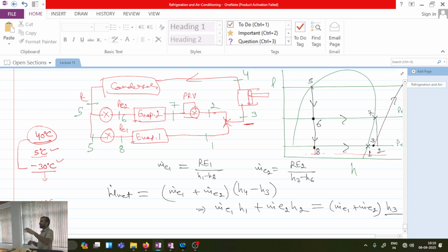As long as we keep on decreasing the pressure of the lower evaporator, what will happen? If I just do the expansion from the same state, then the throttling loss will keep on increasing. At the entry of the lowest temperature evaporator, we will find there is a large amount of vapor. This large amount of vapor will of course have two negative effects.